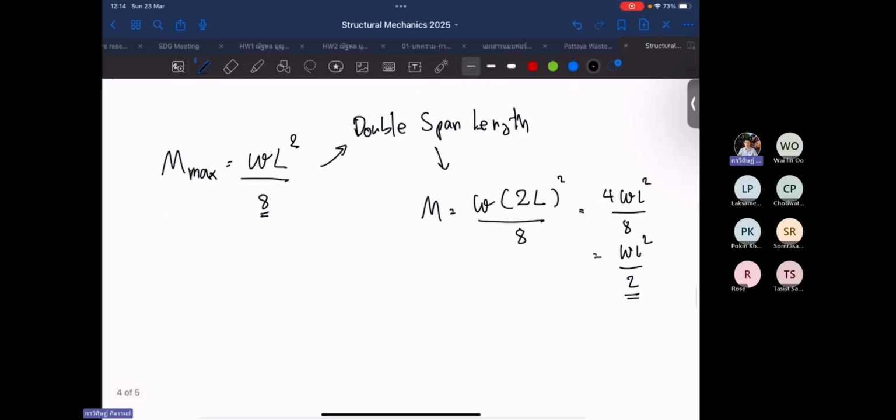In other words, many architects would like to have the longest span possible. But we engineers, if we add one support at the middle of the beam, can cut the moment by 4 times. Let me show you a calculation.